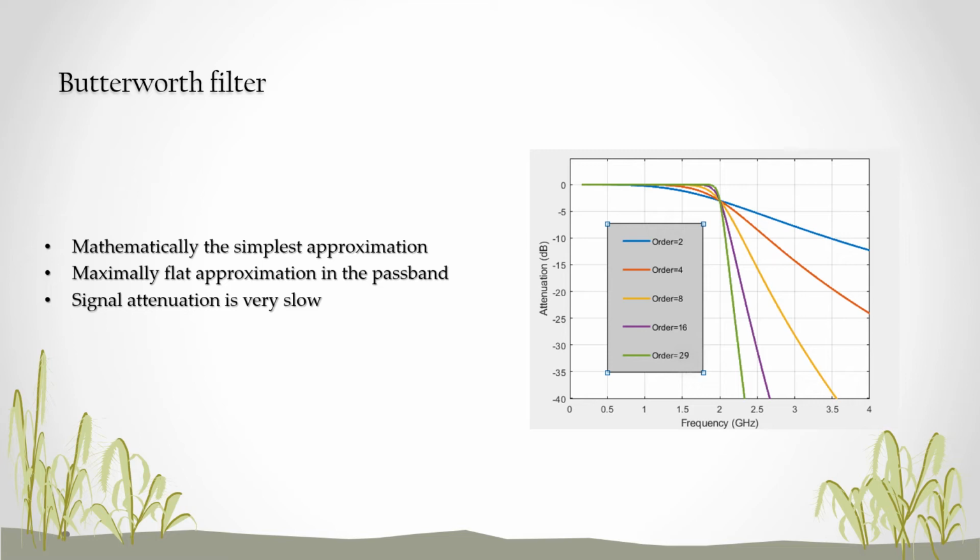Its function is also often referred to as maximally flat, no ripples response, because the passband is designed to have a frequency response which is as flat as mathematically possible from 0 Hz until the cutoff frequency at -3 decibels. Cutoff frequency in our case is at 2 GHz. Higher frequency beyond the cutoff point rolls off down to 0 in the stopband at 20 decibels per decade.